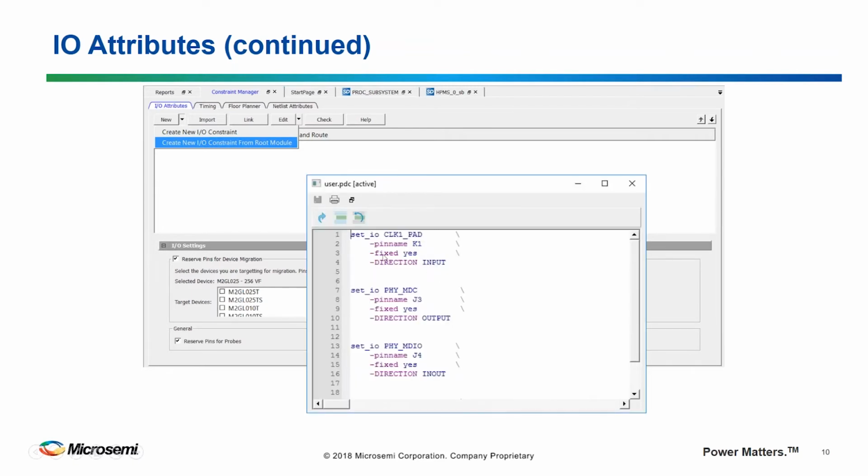will list all of my ports with some of the parameters, the name, and the direction, and then I can go in and I can put in my pin assignments. So I can use a text file, which I could save. I could import it at a later time. I could import that using a Tcl script if I wanted to. Or I can use the graphical tools after synthesis.